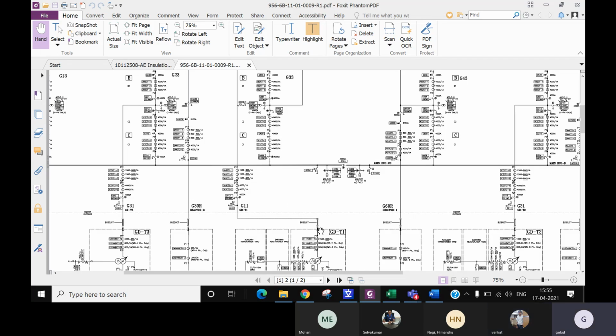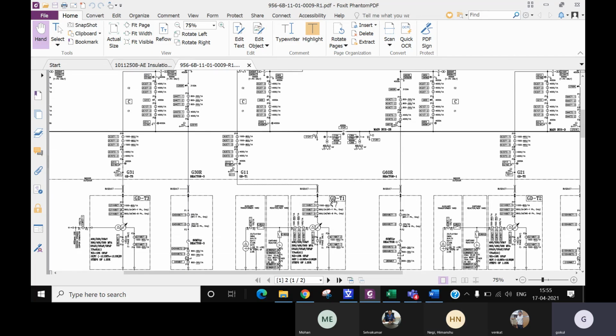Correct. So, transformers and VTs. The cases you are going to perform, the first thing you have to look at is your system. If your system has a VT or a transformer, then you can simulate for ferroresonance. And there are some considerations to be made while doing it in PSCAD.